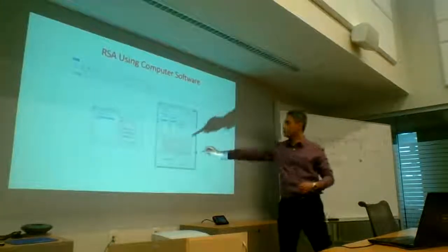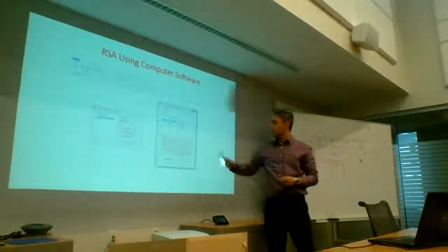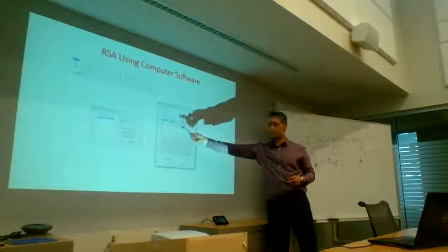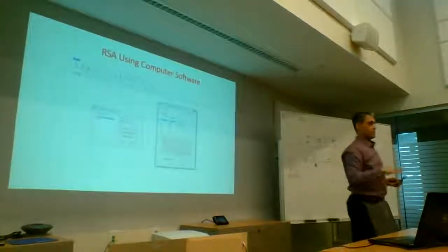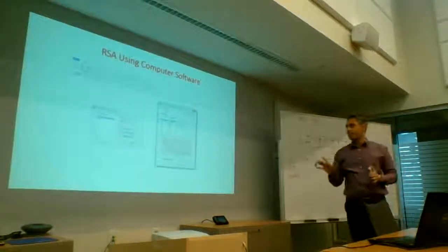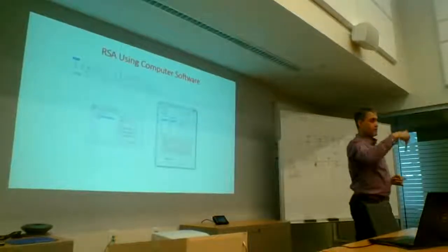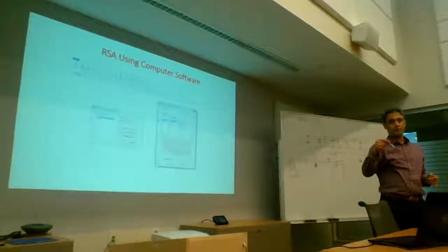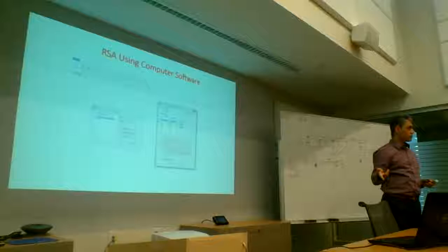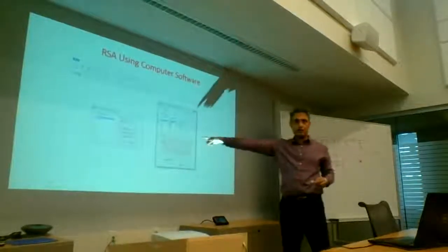You have to input your response spectrum. Here, one mistake I tend to make is, for example, in CSI Bridge, when I put these as 0.61, 0.54, those are just numbers, so those are unitless. So if I put it like this, when I go into the load combination, I have to specify a factor of 9.81 meters per second squared to tell the program. Some programs might just take this as percentage of G and you're fine.